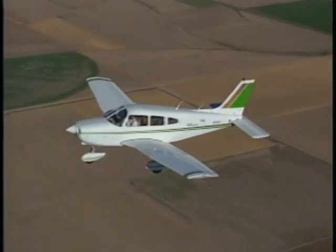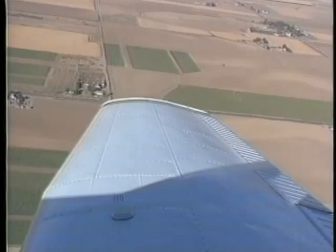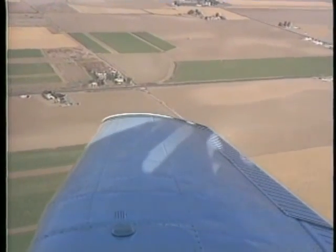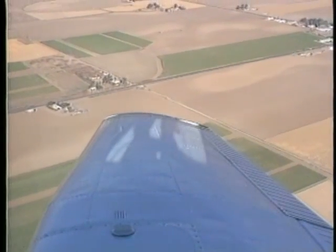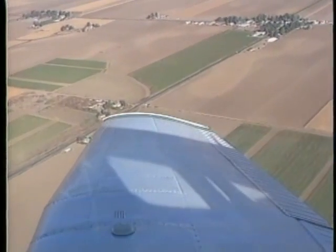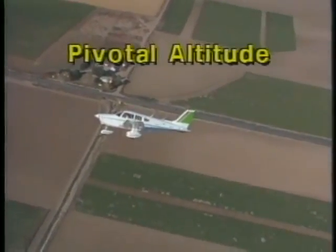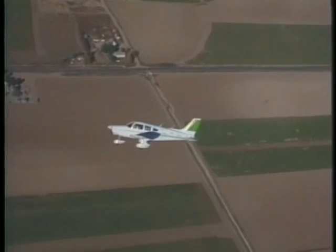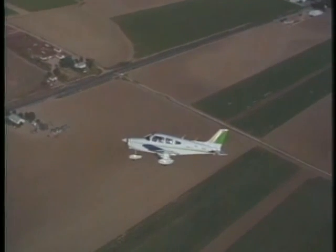This reference point varies depending on your sitting height and position and the wing design of your airplane. Regardless of its exact position, the key to selecting the reference point is that your line of sight through the point must parallel the airplane's lateral axis. When performing 8s on pylons, you should maintain the reference point on the pylon so the airplane appears to pivot about it. The altitude that enables you to do this is called the pivotal altitude, and it is governed by your ground speed. As your ground speed increases, the pivotal altitude increases. Likewise, a decrease in ground speed causes your pivotal altitude to decrease.